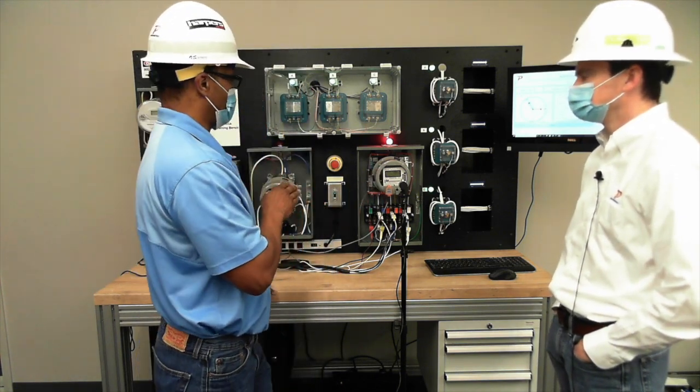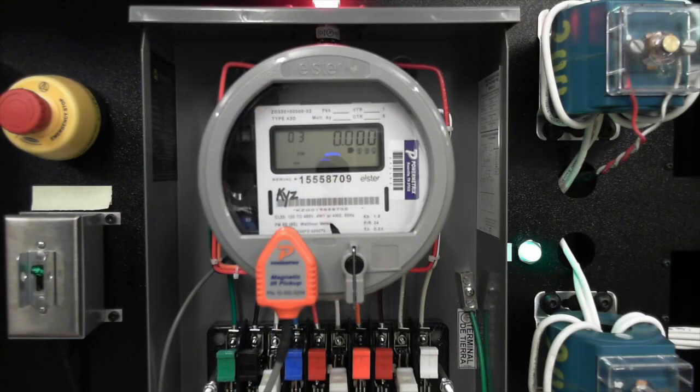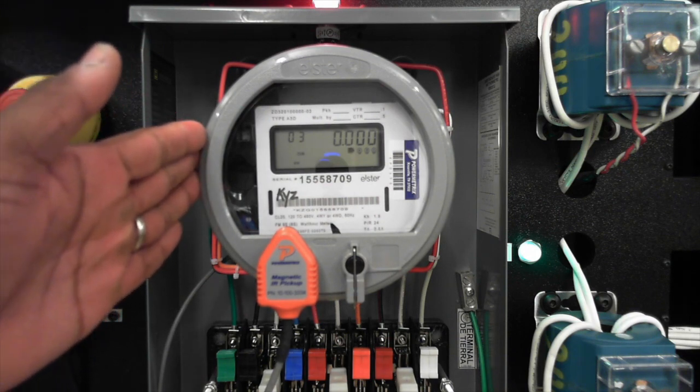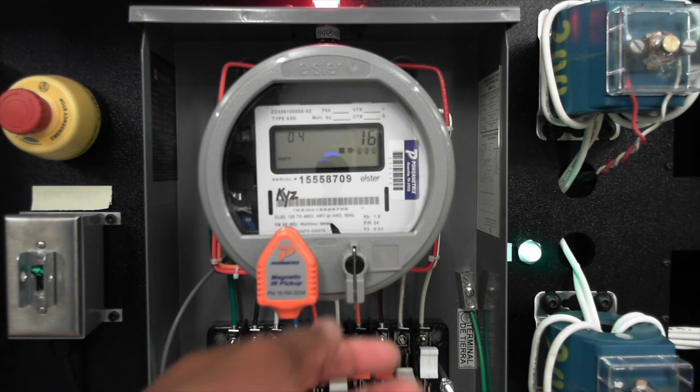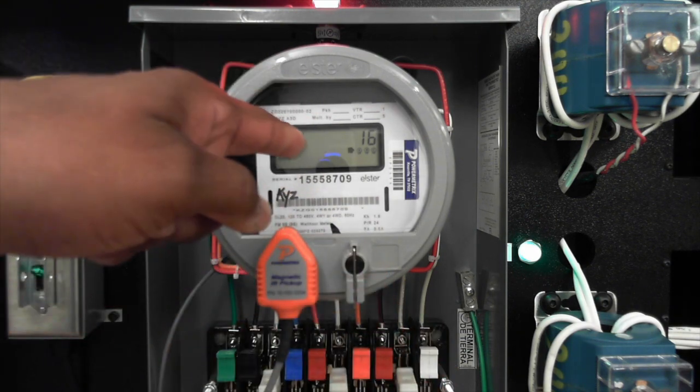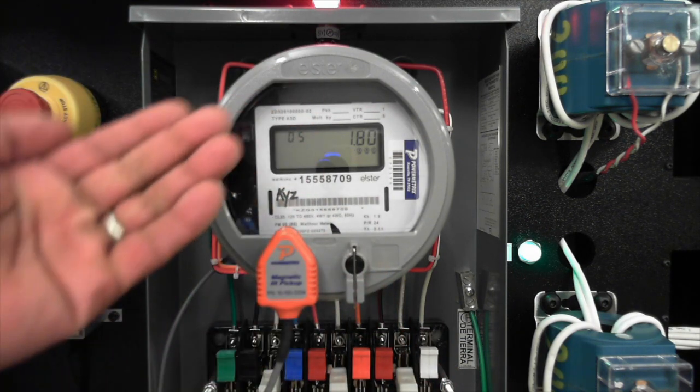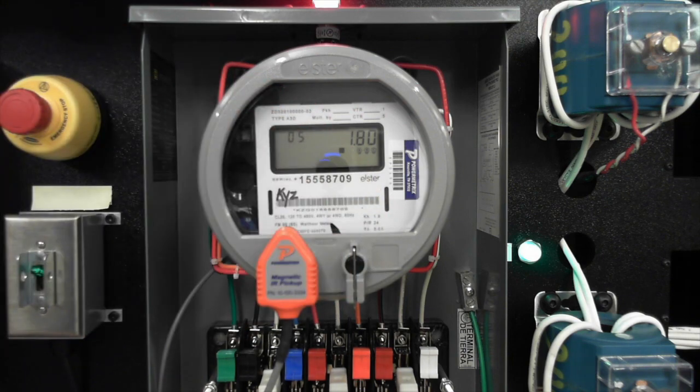So if I was going to test the meter, I would definitely put it in test. But if I was going to reset that meter, I always like to do it with it not being in test, so I can actually see that it's doing what it's supposed to do. Okay. So again, if it's not in test mode, it is critical to communicate the as found, as left kW read before you leave the site. For sure.